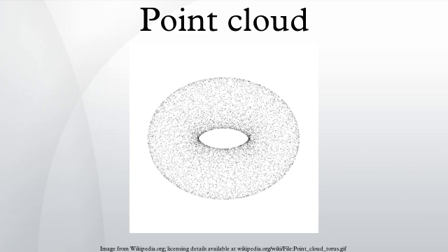One application in which point clouds are directly usable is industrial metrology or inspection using industrial computed tomography. The point cloud of a manufactured part can be aligned to a CAD model, and compared to check for differences. These differences can be displayed as color maps that give a visual indicator of the deviation between the manufactured part and the CAD model. Geometric dimensions and tolerances can also be extracted directly from the point cloud.